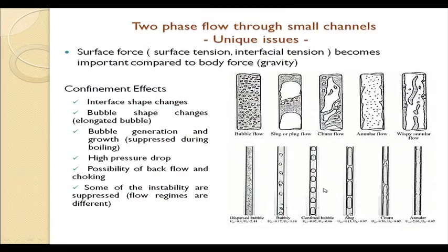The main thing I should say is that for microchannels, we get very similar sorts of distributions, but we understand that there is a difference and a need to differentiate between these flow patterns. We do not have sufficient words, or in other words, not much information from macro channel flow can be used in this case. For example, both of these are more or less bubbly, or bubbly slug, etc. But there is a definite difference between the distributions.